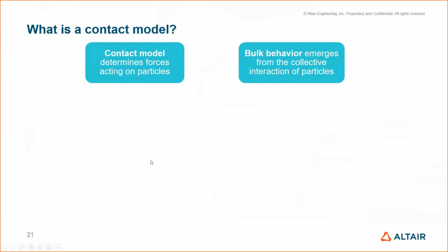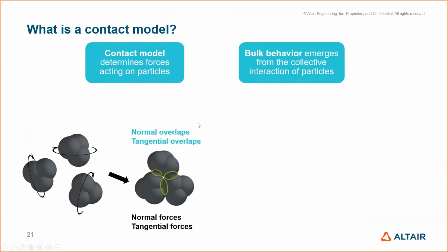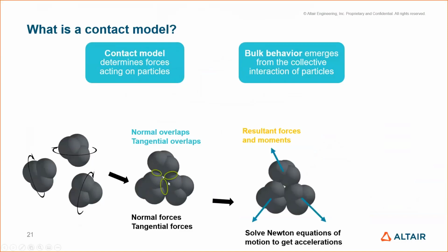So what is a contact model? I've mentioned this a few times. The contact model is a model which calculates a force when the particles are in contact, and generally speaking, not always, the force is based on the overlap. And the overlap results in forces and moments, which gives us the final velocities.